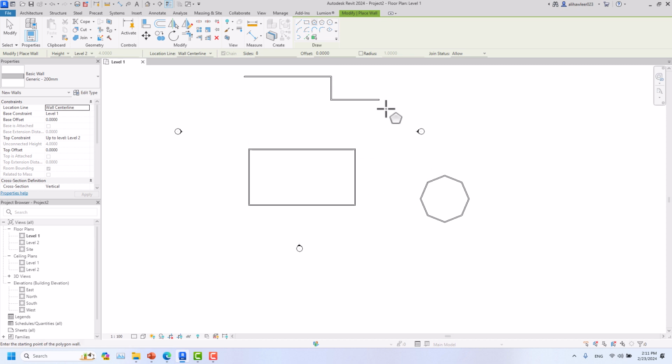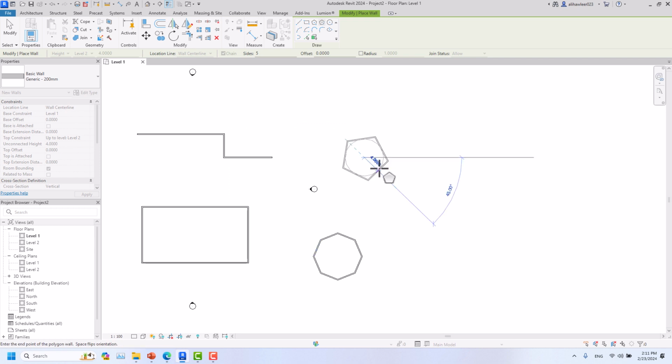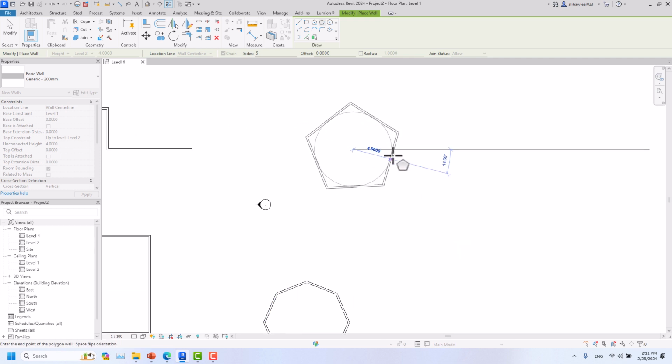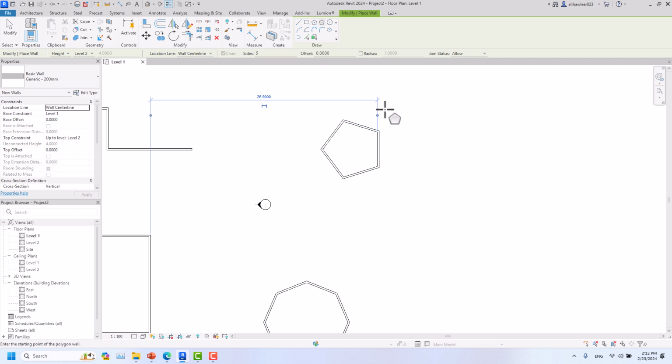Okay, so let's go to the circumscribed polygon. This one is inserting the circle inside the polygon. This is actually versus this. So circumscribed, I'll click on it and this time it says how many sides. I'll say 5. Let's make a pentagon. This was octagon and just click on it and you can see your circle this time inside it. Okay, so this time I'll make it 3. And yeah, we created our circumscribed polygon, and this is inscribed polygon.